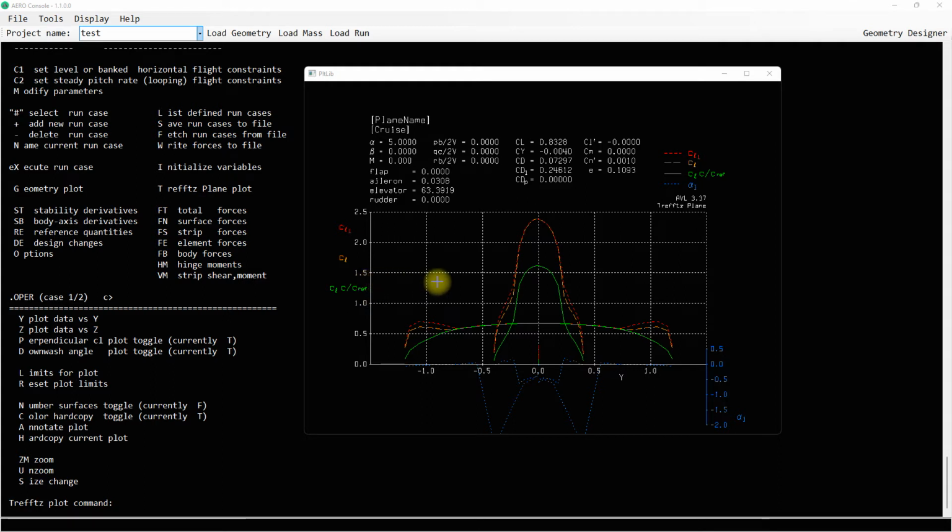more than 1.3 CL. So the orange line, we said the dash orange line is the CL. So we see at these sections above 1.3, whatever is in the middle of this airfoil section or wing is experiencing or maybe experiencing the stall. So to avoid this, you can change your flight conditions to bring everything below the stalling CL or angle of attack, and otherwise you would have to change your geometry or other flight conditions to be able to bring that back to below the stalling conditions.